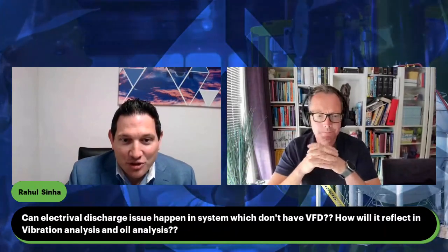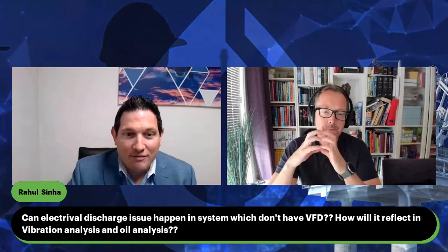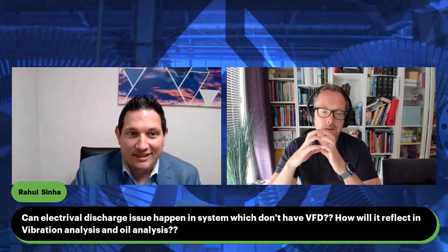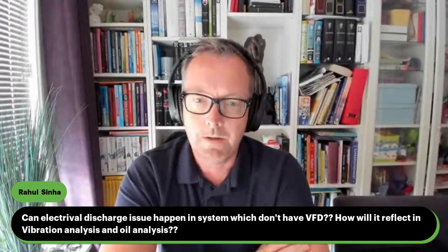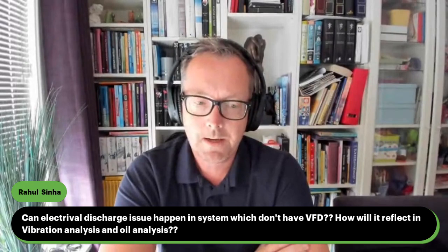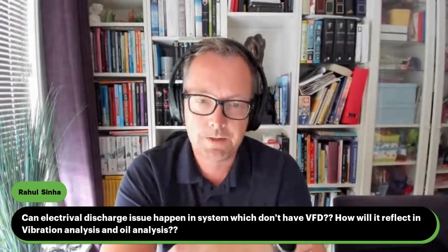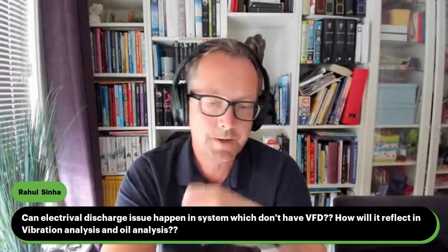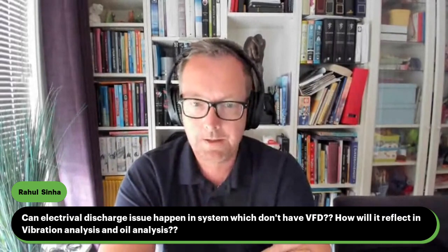Okay, good. So we have a question from Rahul. Essentially, can electrical discharge issues happen in a system which doesn't have a VFD? And how will it reflect in vibration and oil analysis? We have seen it in basically all kinds of systems, really. I read some reports from the drilling sector, where there have been a bunch of fires in the breathers on the small hydraulic systems out there. And wherever you push oil through a filter, this can happen.